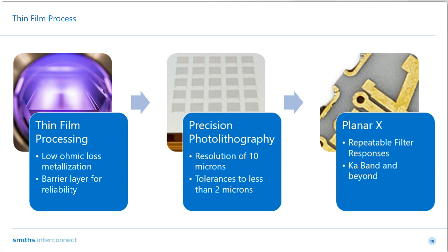In order to meet the market demands using the Ku band, the printed filters need to be very small and controlled geometry. One method to attain this is with thin film processing, which can support geometries as low as 10 microns. The filter is designed on a low-loss tangent substrate with a high relative dielectric constant. The pattern determines the filter's response, and the metal used must be highly conductive for low loss.